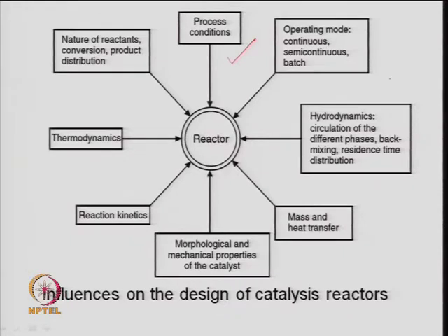So, similar properties can be used to study the hydrodynamics under those cold flow conditions. So, physicochemical properties of the system should be the same, and one can do the CFD of that and look at the flow behavior in terms of the non ideal parameters, and that helps in improving the efficiency of the reactor. So, all these terms are important when we look at the reactor design.